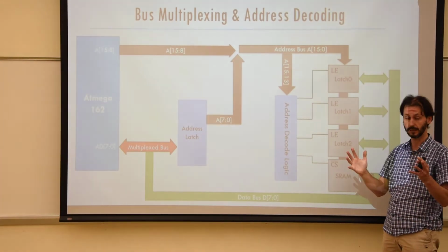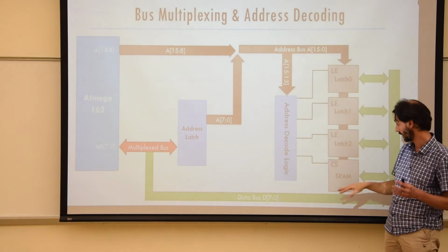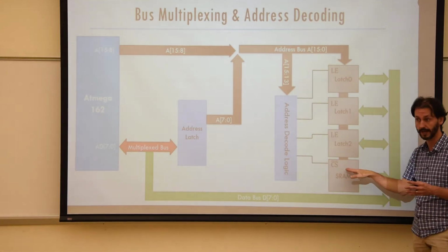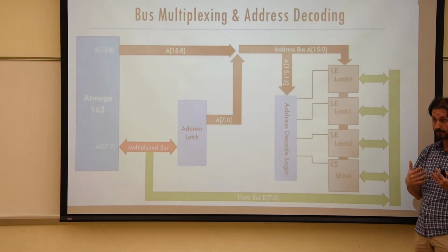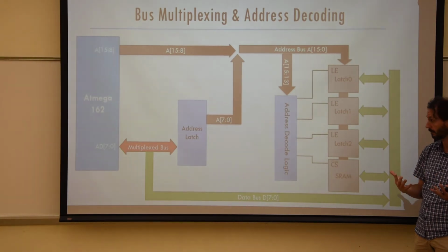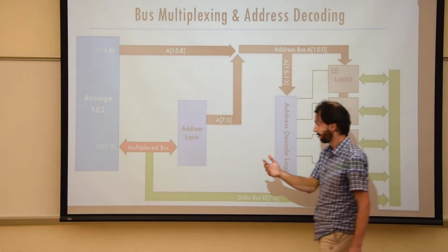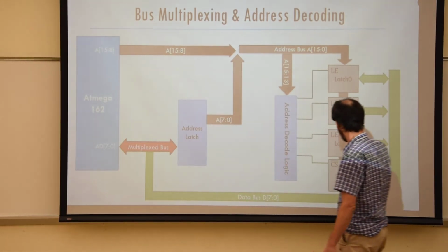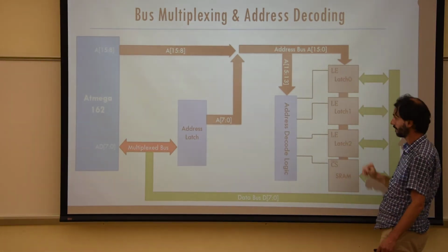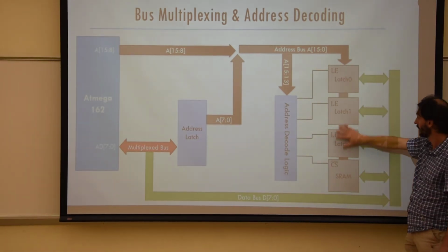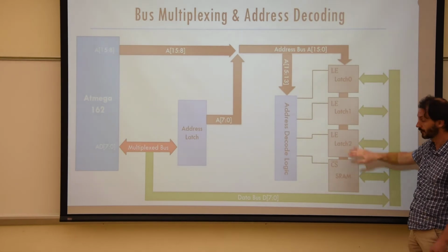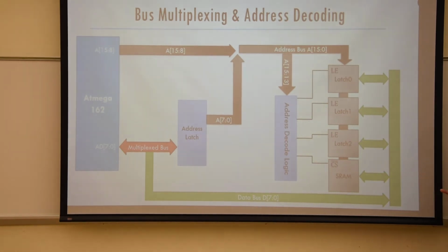And you can look at the data sheet, you see this diagram, and you need to look, of course, at the data sheet for your SRAM. You need to find out how many wait states you need to include in order to make it work. Now once you understand how this works, you can add a bunch of other peripherals. Here we call these latch 0, latch 1 and latch 2, indicating 3 strips of 8 LEDs.